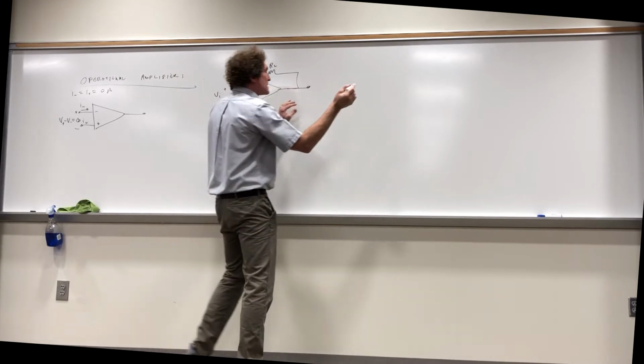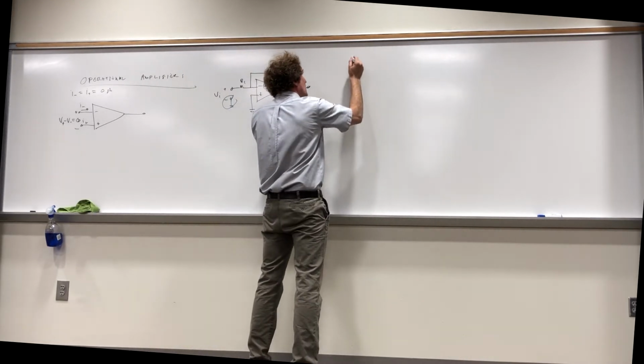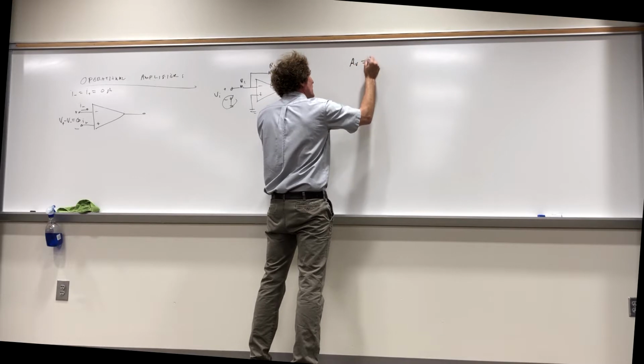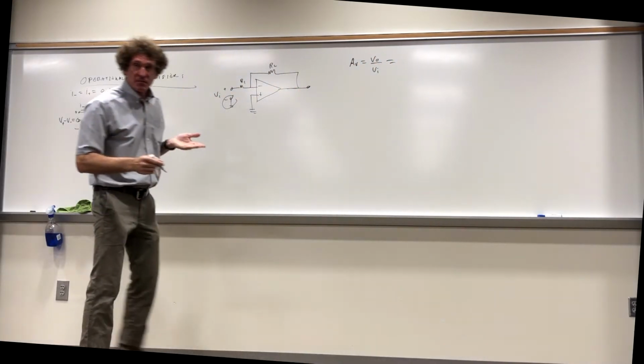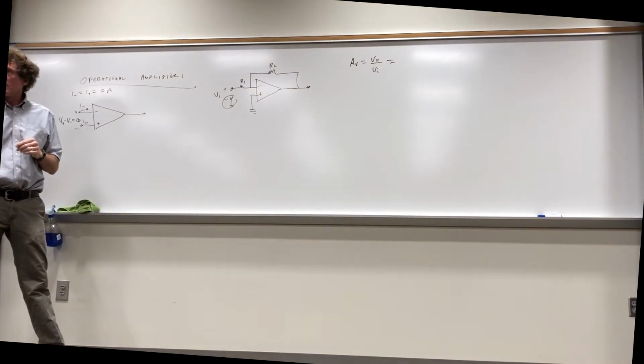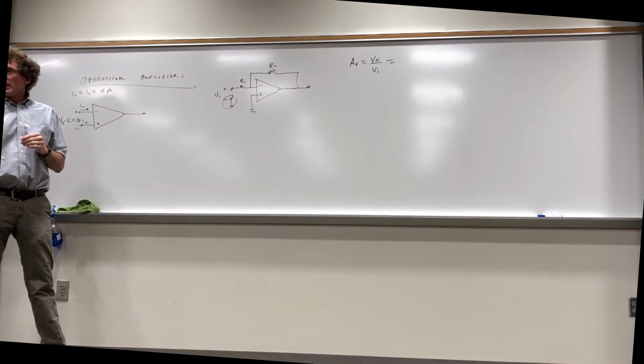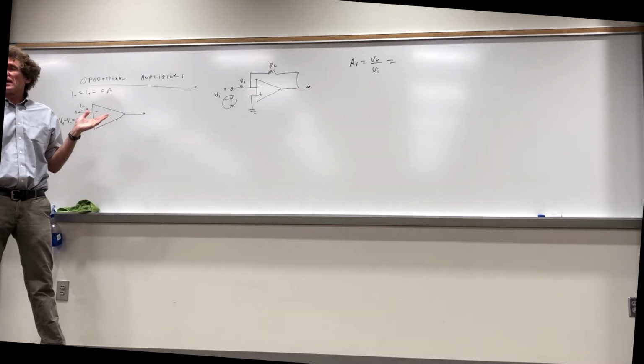We did this one last time. And what they really want is something called a voltage gain, AV. They want V out over Vin. This is a transfer function, if you think about it. Output over input voltage is a transfer function. It would be called our H of S. In this case, it's not a function of S. Everybody with this?